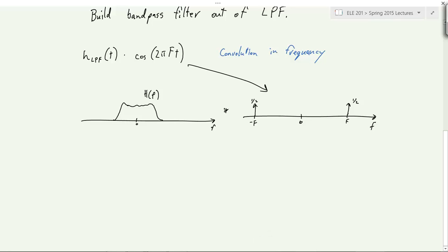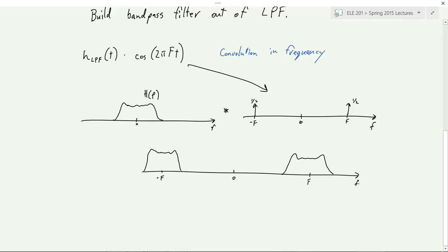you're going to do a convolution of these. And so the result is you'll get this. Whatever. That and that. Okay. At frequency, centered at the modulation frequency. Now, this is not necessarily any better than the idea that was just suggested of doing a low pass and a high pass. It's nice that there are so many different ways to interpret. Well, once you're comfortable with the Fourier transform properties, there's many different ways to design and to interpret designs.